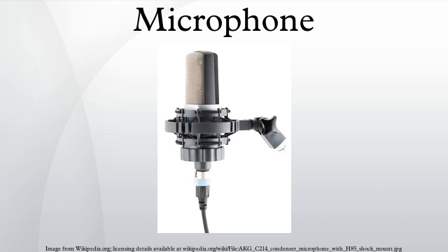Condenser microphones span the range from telephone transmitters through inexpensive karaoke microphones to high-fidelity recording microphones. They generally produce a high-quality audio signal and are now the popular choice in laboratory and recording studio applications. The inherent suitability of this technology is due to the very small mass that must be moved by the incident sound wave, unlike other microphone types that require the sound wave to do more work. They require a power source, provided either via microphone inputs on equipment as phantom power or from a small battery. Power is necessary for establishing the capacitor plate voltage, and is also needed to power the microphone electronics.